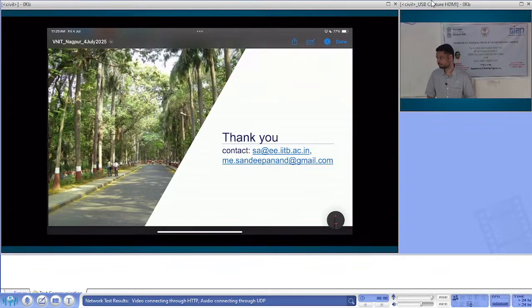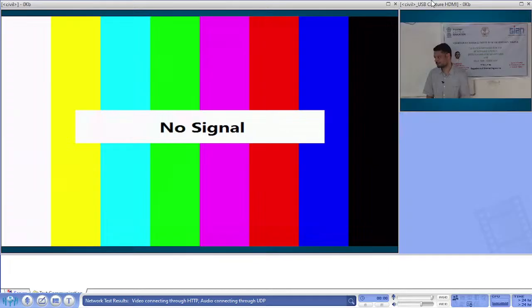So when we are saying fast charging, what is the time frame that is considered? Yeah, I think that definition is, of course, now UID has come and now 5 minutes is the definition, but earlier it used to be 1 hour. So I think that's more of a term loosely used to represent you are doing 1C or higher charging. 1C means you charge in 1 hour or faster. So I think that's typically how people would use it.